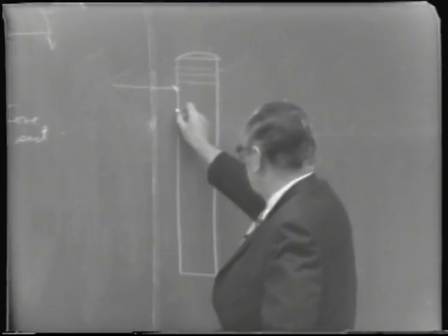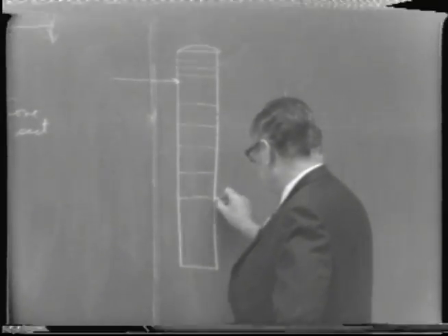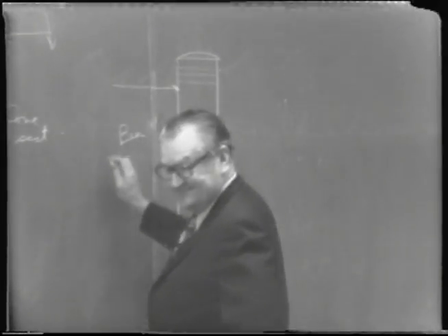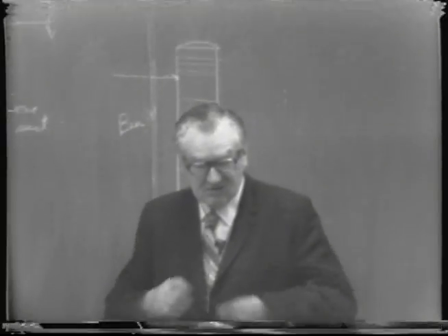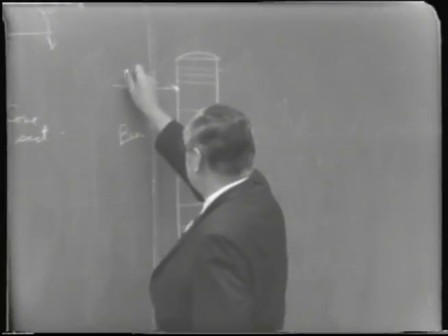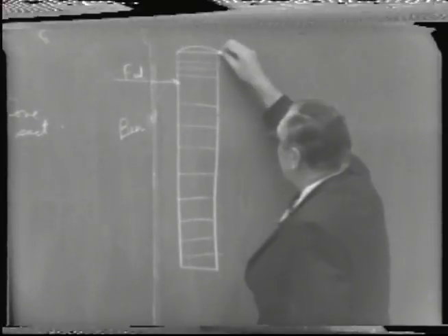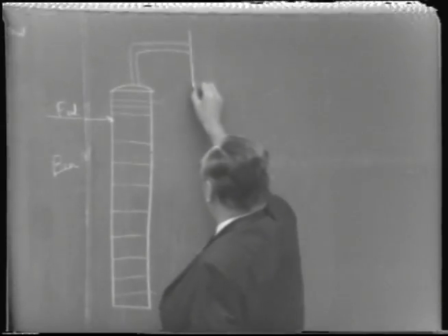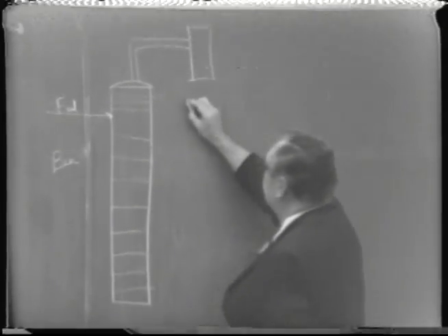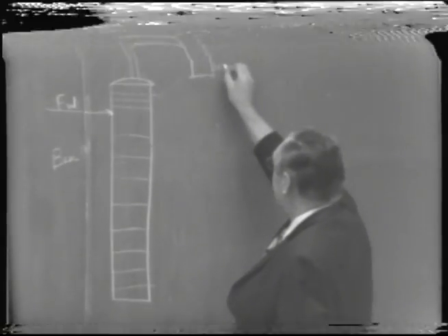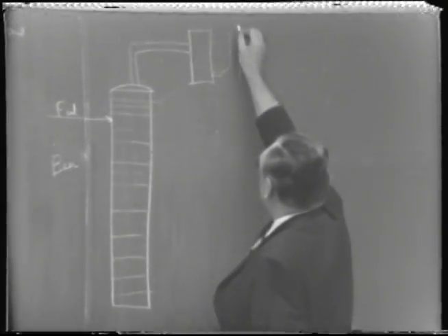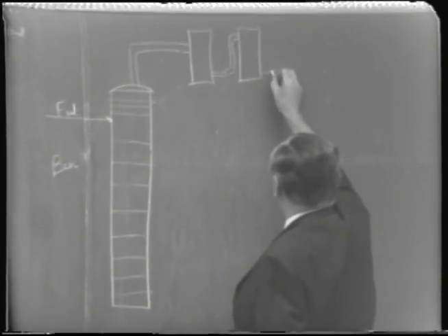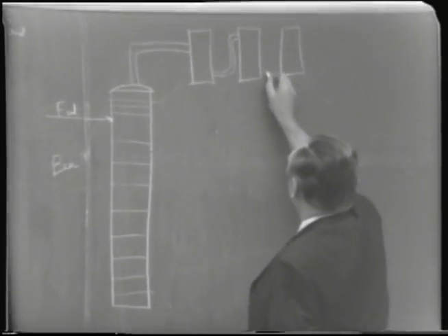But primarily it's a perforated plate column, which is intended to recover the alcohol out of the beer. Beer is a term for fermented grain mashes. But anyway, this would be the feed. Now then, this vapor going off here is condensed. Usually there's about 2 or 3 of these condensers. The first one of which is usually a preheater. And so I'll just draw in here 3 of them.